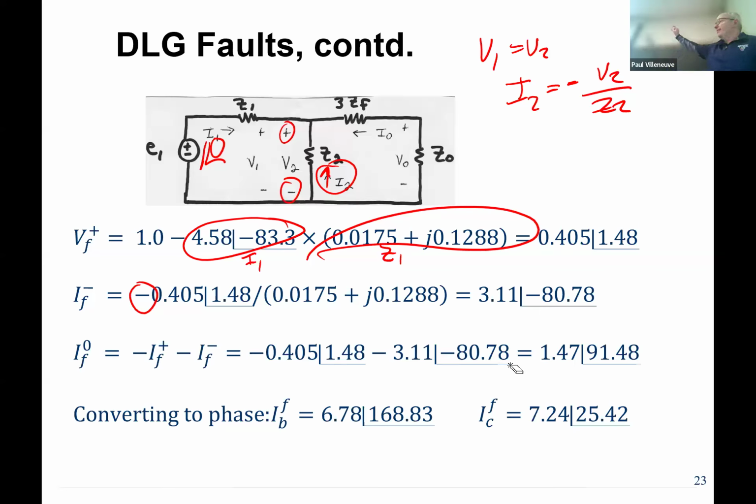But when you're actually setting the relays for a single line to ground fault, or double line or whatever, then you have to start doing a lot more nuances. And by far, out of all the work I've done, the hardest protection to set is ground fault settings, because you have mutual coupling between zero sequence networks.